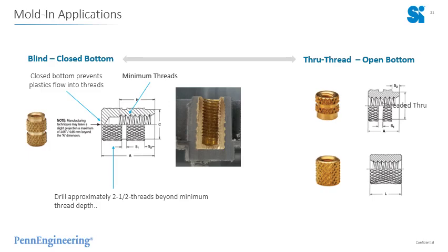Of course, you can use through-threaded inserts with this installation method. It's important to ensure that the tolerance of the pin you're using has a very tight tolerance with the thread minor, and that'll prevent plastic from creeping into the insert.